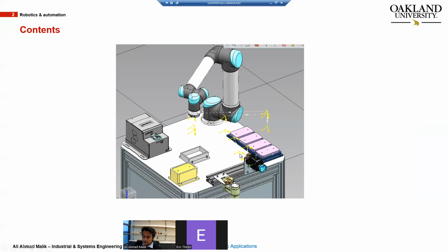And then for each of the components, you need some fixture or some method by which they are presented to the robot. If you are using a fixture, then you don't need any camera, etc. So the robot knows where each component is placed. Each location you have fixed, which is why we call them fixtures. By defining coordinate values for each component's location in the robot program, the robot knows how to pick and place them.